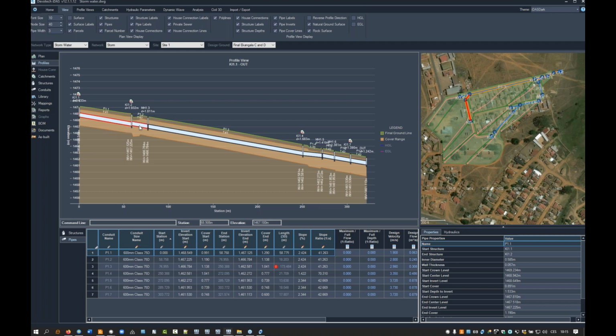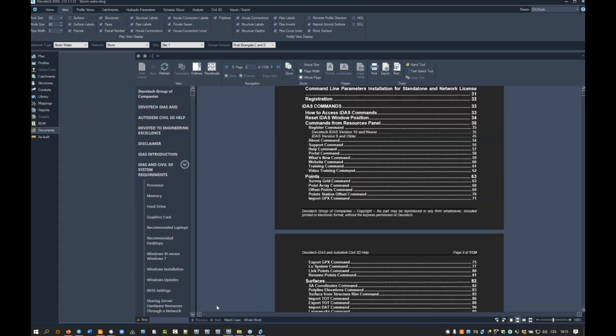If I select those two, I can regrade with another keyboard shortcut. So you see it works like that, stays together. So those are editing options which were available for sewer before, but now they are available for stormwater as well. If you want to explore a little bit more about those editing options, the keyboard shortcuts I'm using right now, like control and alt with the combinations with the keystrokes on my numeric keypad, you can always go to the help file. And the quickest option is to go to control F to find, and control +9.